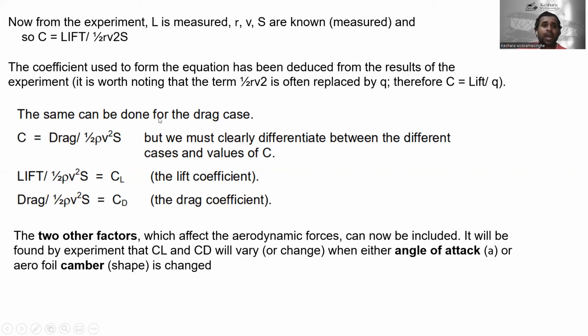The same can be done for the drag force. So there is a drag coefficient also, right? You can see this one, drag divided by Q. But we must clearly differentiate between the different cases and values of C. Lift divided by Q equals the coefficient of lift, and here the coefficient of drag. Okay, this is the lift coefficient and this is the drag coefficient.